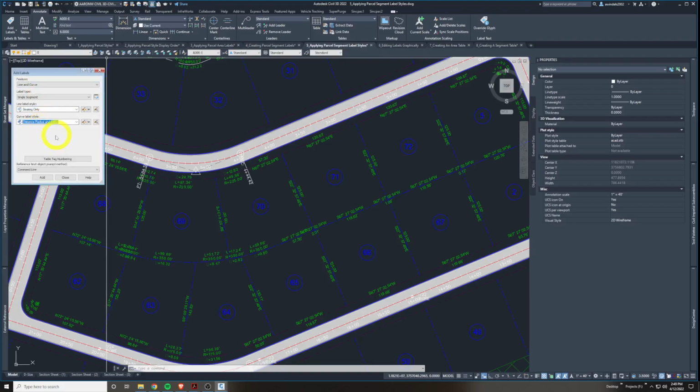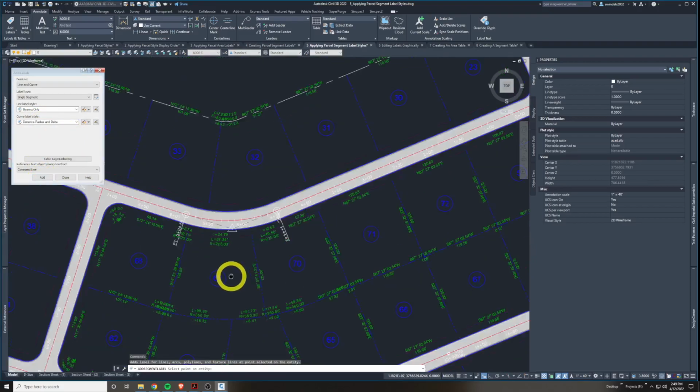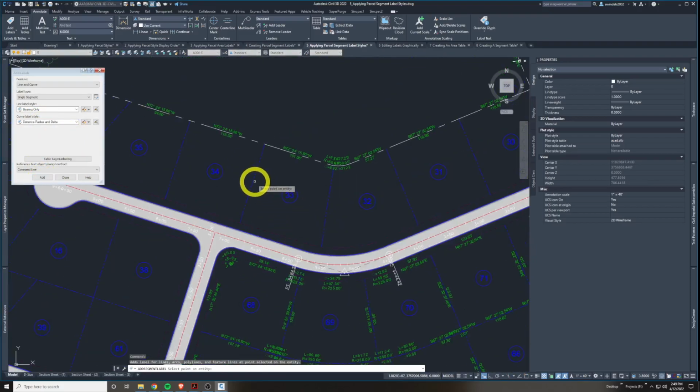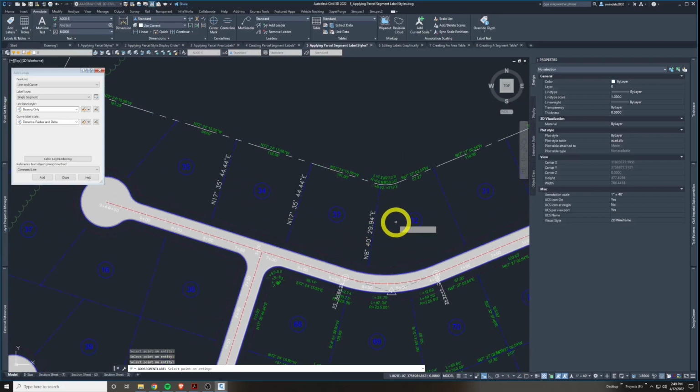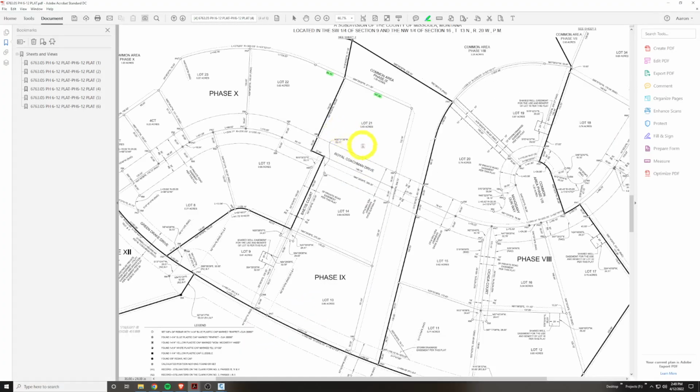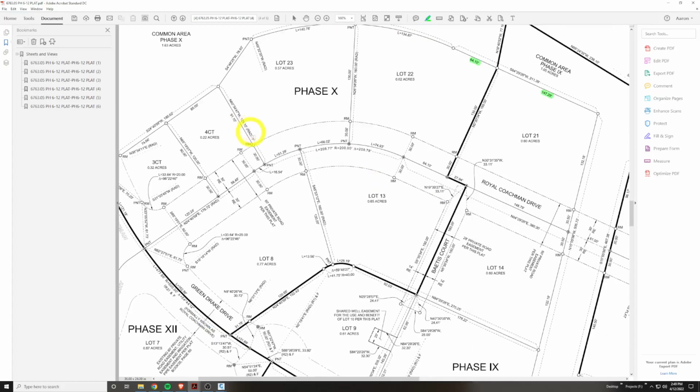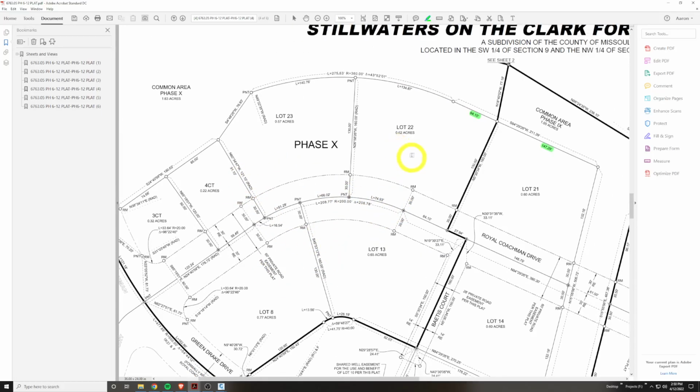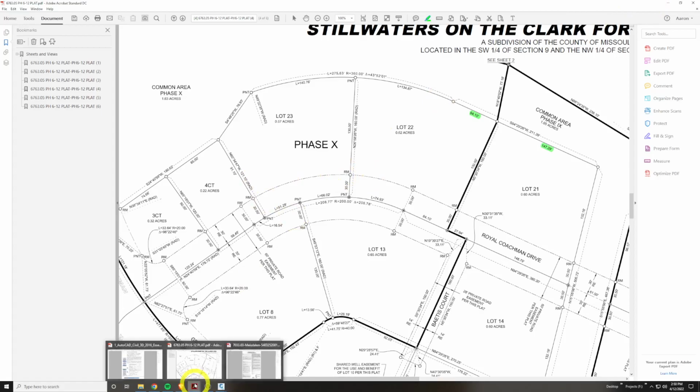I often do this when I don't use parcel features and I just want to annotate lines and polylines. We can also annotate using these, which I often do on jobs that have very unique geometries all over the place, but also design parcels. So I mostly labeled this with lines and curves, but line and curve labels are almost similar to parcel labels. Think of them as the same things, line and curve labels and parcel segment labels. The end result is similar, annotation of lots.